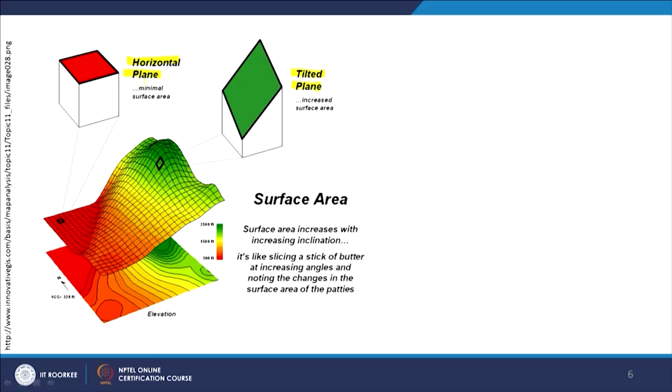This is going to be the minimal surface area if it is flat, or when it is measured on a horizontal plane, whereas where there are sloping surfaces, the surface area will be increased compared to the planimetric area. The cell, in our raster format or digital elevation model, represents a square area, but that square is not truly a square on the ground; it is a surface area.